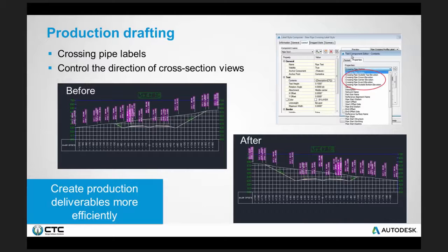Production drafting, some small, much-needed improvements there. Crossing pipe labels, needed that for a while. This is in both profile view and in cross-section view. So we can have perhaps a sanitary line crossing a sewer line, and we have a profile along the sewer line. We want to not only see that crossing pipe of the sanitary line, but we also want to label the exact invert, or perhaps the outside top and bottom of pipe at that crossing location. We didn't have that option before. We do have that now.